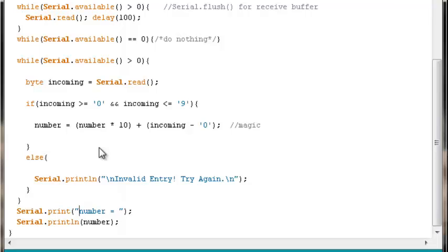What is happening is this is running so fast that Serial.available gets triggered, and that 1 in the 15 gets sucked in, passes the if test, gets converted, stored in number, and this is going around so fast that before it can pull another serial read, pull the 5 in, it actually ejects.